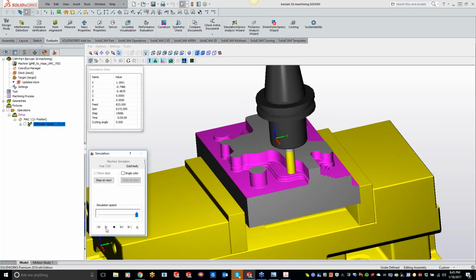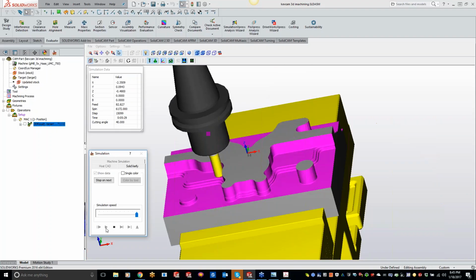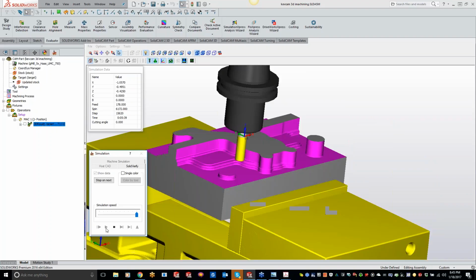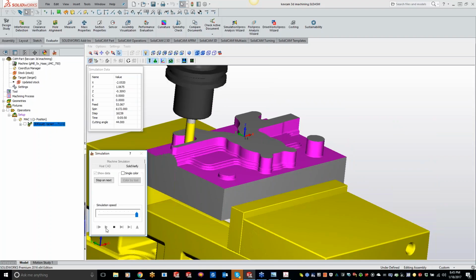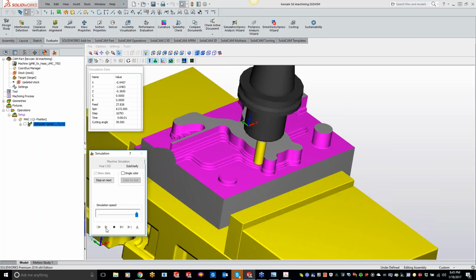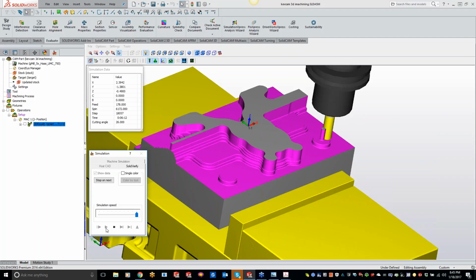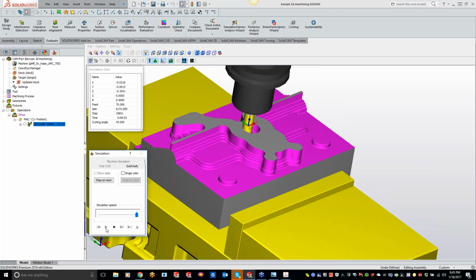But iMachining is smart enough to know what's already been cut. So what it'll do is actually slow the feed rate down, but still maintain that chip thickness in order to break through that wall. Did you see what I was kind of talking about there, Kevin? Yep. That's what we call, maybe you could explain that a little better than I could.